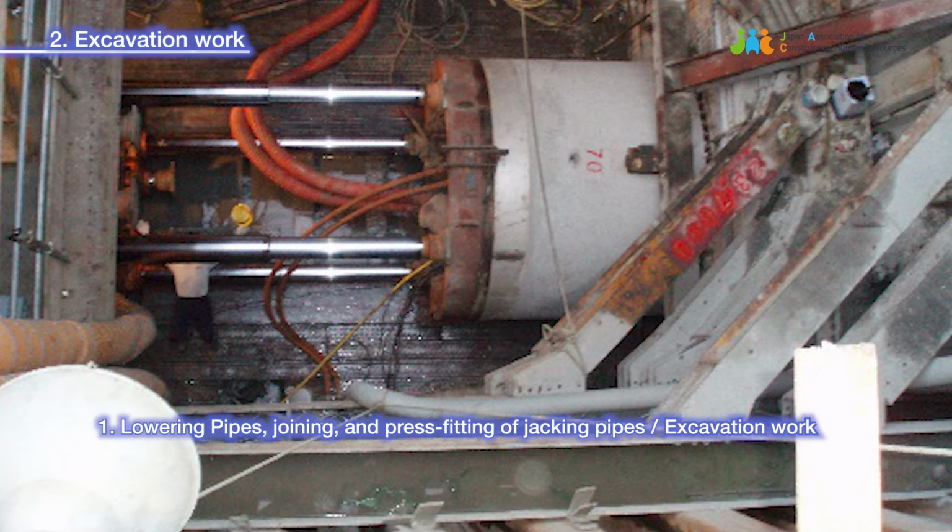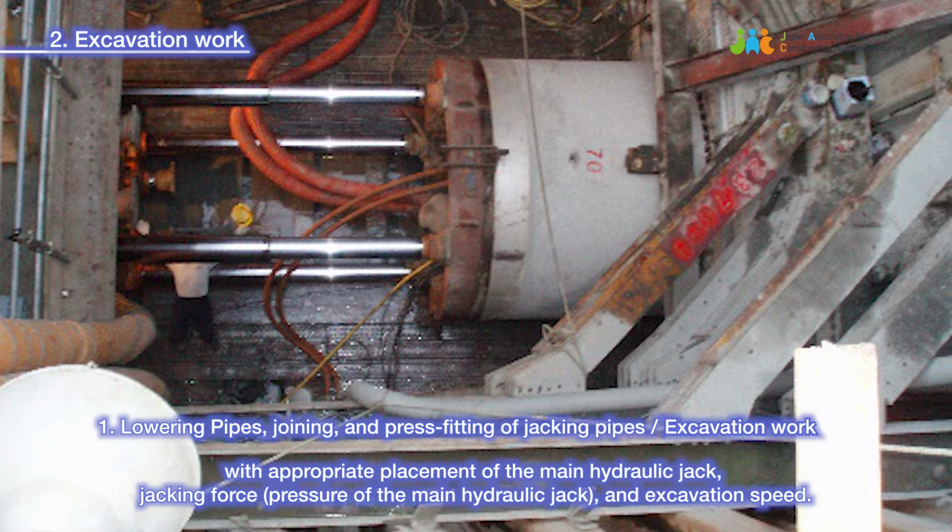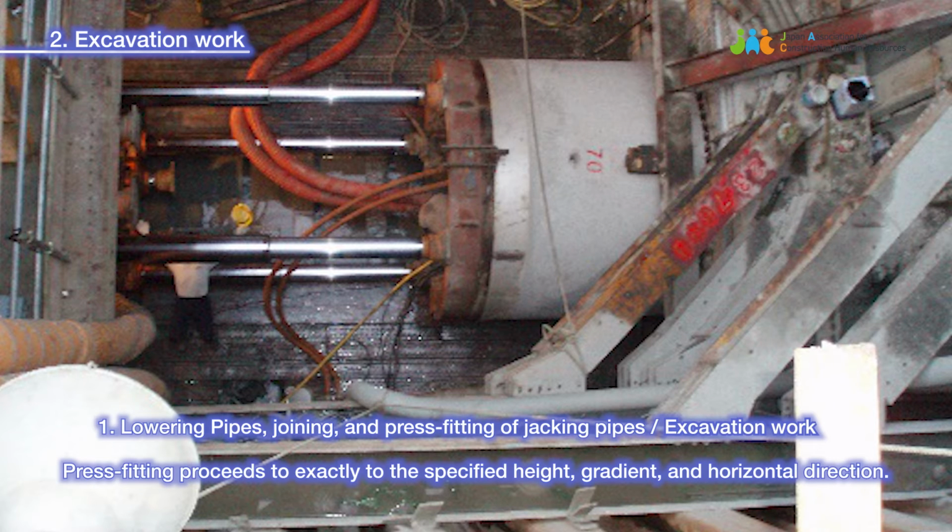Excavation work. Excavation work is carried out depending on the soil quality of the ground, while stabilizing and protecting the face, jacking pipe, reaction bearing, etc., with appropriate placement of the main hydraulic jack, jacking force, pressure of the main hydraulic jack, and excavation speed. Press fitting proceeds exactly to the specified height, gradient, and horizontal direction.